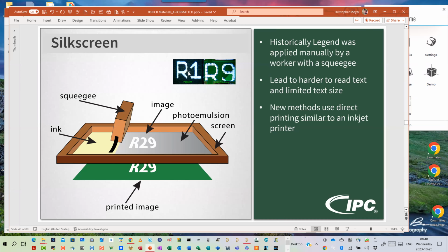That's the same spread of liquid we talked about with the solder mask, where the surface tension of fluid wants to form that little dome, so it's going to want to spread out a little bit. We have the same thing here. Historically, if I tried to make characters too small because of that spread of the ink, I would run into problems like the opening in the R would just merge together and I'd have a white blob, and so on.